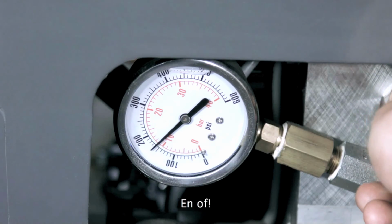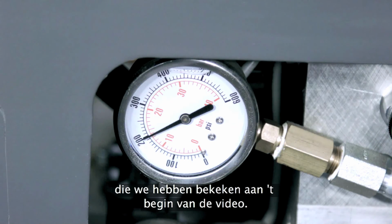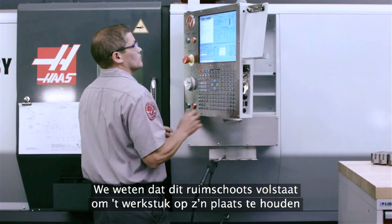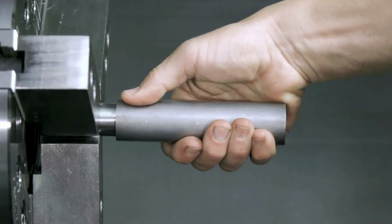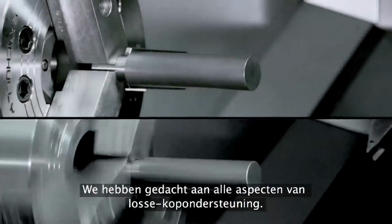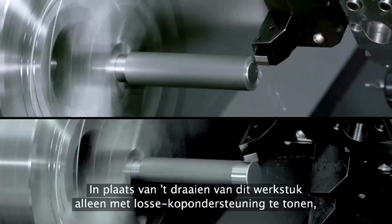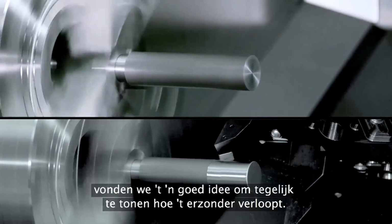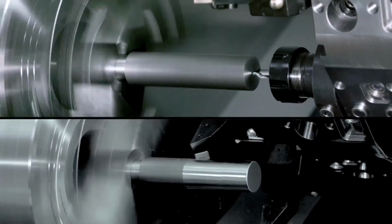You bet. Let's return to the profiled and threaded shaft we looked at the beginning of the video. We'll use a tailstock pressure of 200 psi, since we know this is more than sufficient to keep our part in place without any unnecessary amount of force on our part and machine. With all the aspects of our tailstock support accounted for, we're ready to run our program. But instead of just watching this part run with the tailstock supporting it, we thought it'd be a good idea to watch how it performs running alongside a separate run made without the benefit of tailstock support.